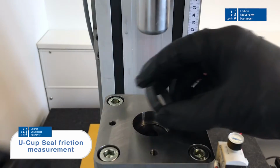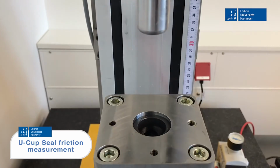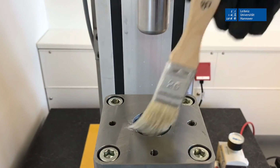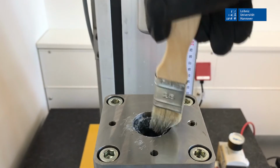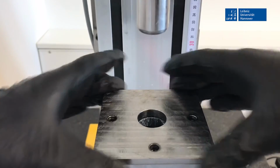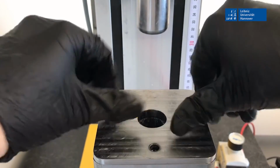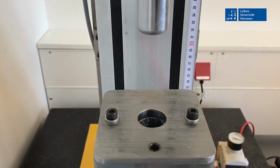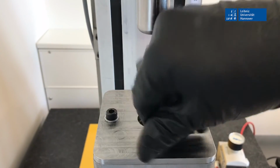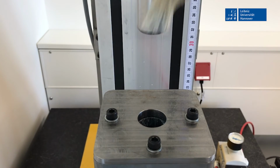The friction measurement procedure of the U-cup rod seals starts with the assembly of the seal in the cap of the pneumatic cylinder. The inner side of the seal, which is in dynamic contact with the rod, is lubricated with the help of a brush. A cover plate is mounted on the pneumatic cylinder to secure the position of the seal. The lubricant is also applied to the rod surface.